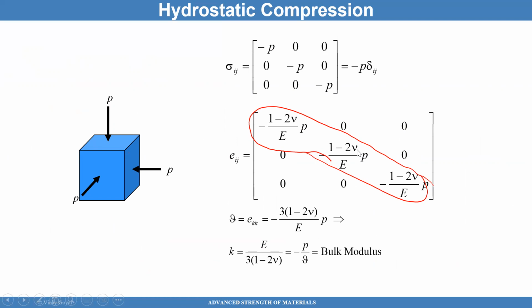And if the Poisson ratio is close to 0.5, like rubber, say, then you're going to get almost no volume change, right? Because nu is 0.5 and 1 minus 2 times 0.5 is close to 0. So if you have rubber and you apply compression in all directions, it's going to be very hard to compress it. But if it was metal, it's a little bit easier. You can see that's the truth, because nu will be like 0.3, not 0.5. And if it is 0.3, then it can have volume change.